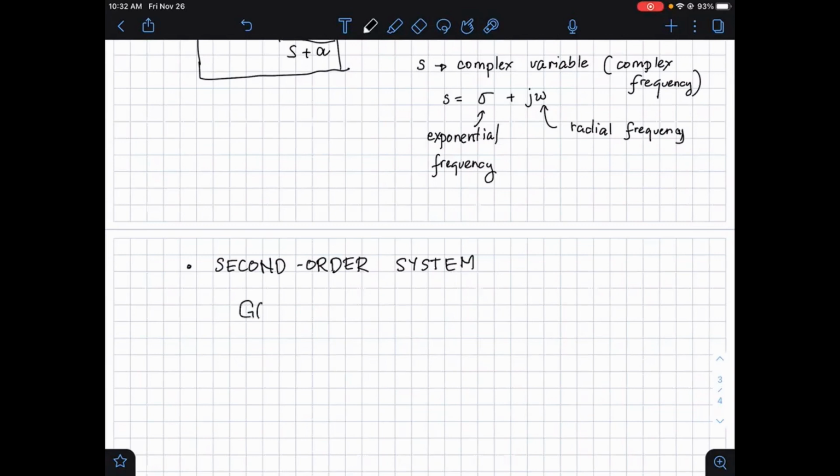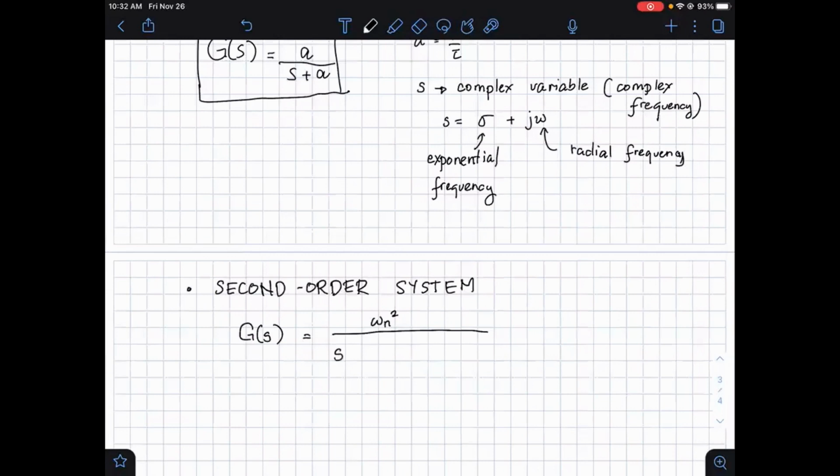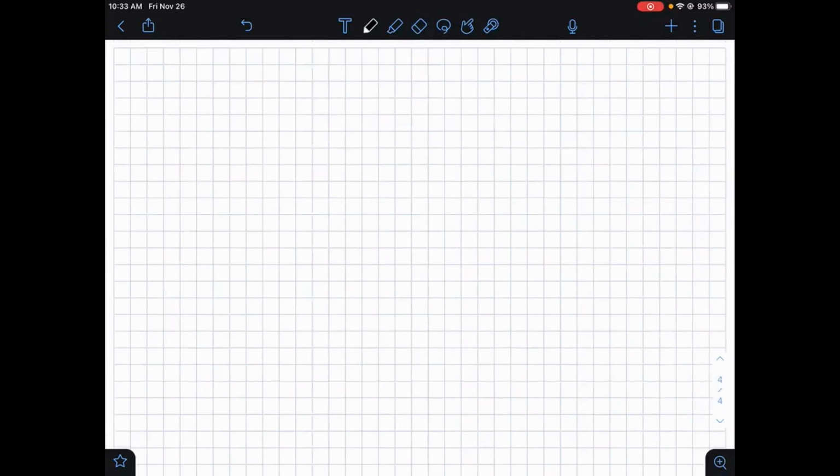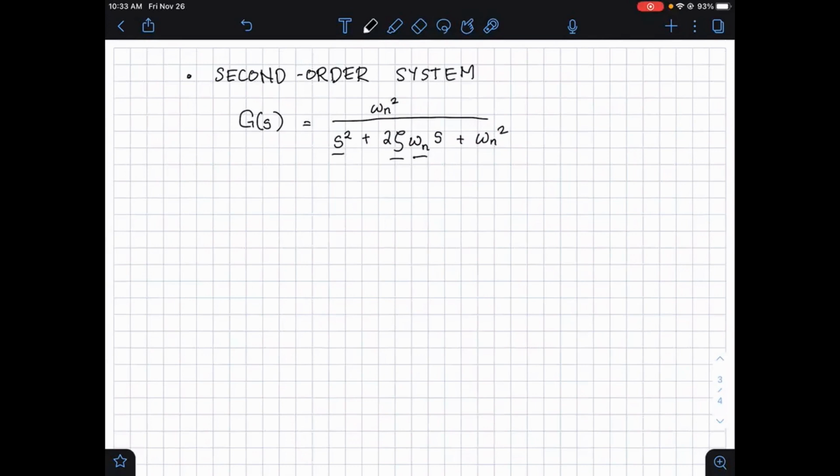Analytically, a second order system would have this form of the Laplace transform or equation or transfer function. So it is second order because the polynomial in terms of the complex variable is second order. There would be a damping coefficient, and again the natural frequency omega is frequency, but it is subscript by n because it's known as the natural frequency. There is s here, and then omega n squared. So you see that the form of the second order system is quadratic, the denominator. And there are two parameters of note: the natural frequency and the damping coefficient.